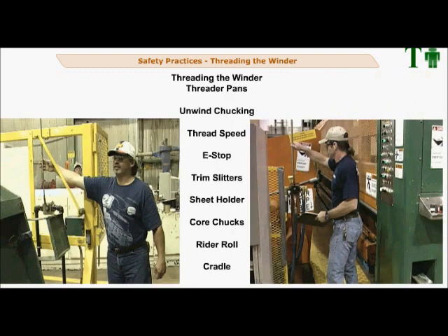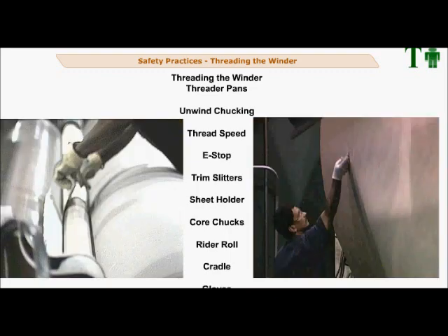A significant hazard exists between the cradle and winder drums. This pinch point has caused fatalities in the past, and Weyerhaeuser has placed additional safety equipment beyond that of the manufacturers to reduce the likelihood of anyone being caught in that nip. There must be an electric device or button to kill control power to the cradle and additional manual hydraulic valves for isolation. These will stop the cradle in its current position. If gloves are worn to protect your hands, they must be tight-fitting gloves. A loose-fitting glove can be grabbed by a nip, especially during threading.